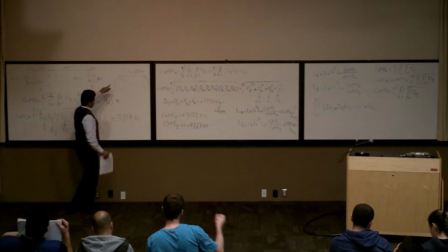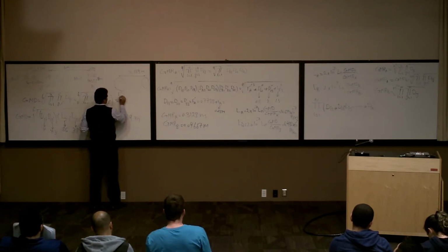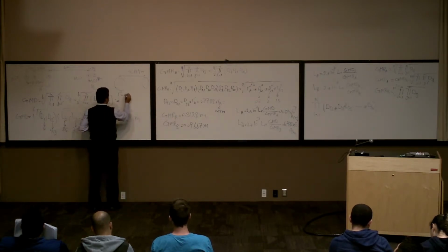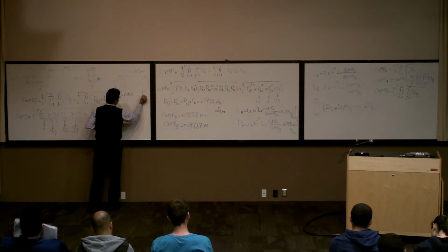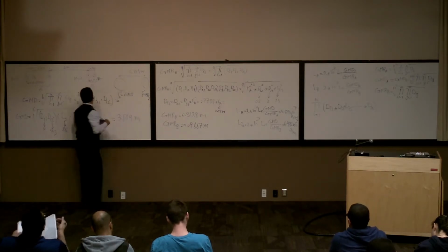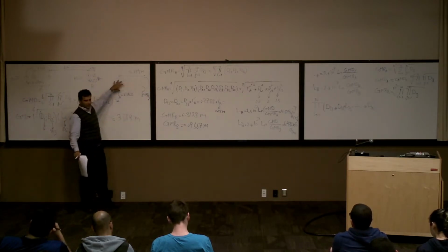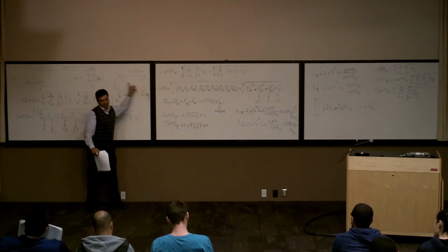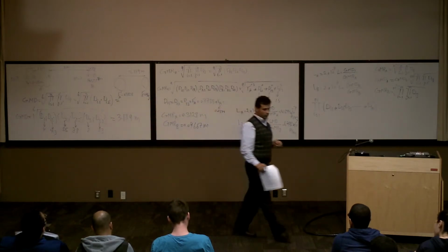So basically, if you're going back here, we are equivalent of two conductors. This one has an R prime equal to this much, and this one has R prime B equal to 0.09667. So this system is equal to this system. This conductor has this much R prime, this conductor has this much R prime, and they're this far from each other. That's the equivalent of that 5-wire system to make it 2-wire.